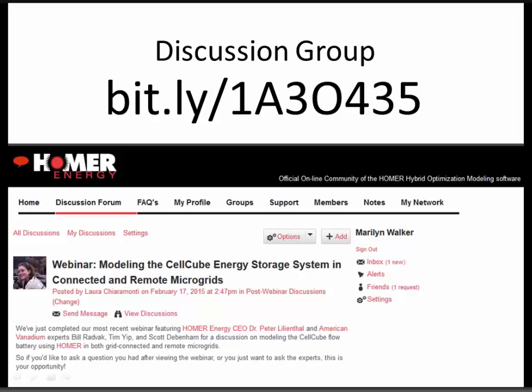So what we're actually doing is running a fuel cell with liquid electrolyte. So it's a very benign operating environment. It's constantly being cooled by this liquid electrolyte, and then the electrolyte is just stored in separate tanks, and it's the size of those tanks which determine how long or how much duration you have of battery. And state of charge is pretty much self-limiting.